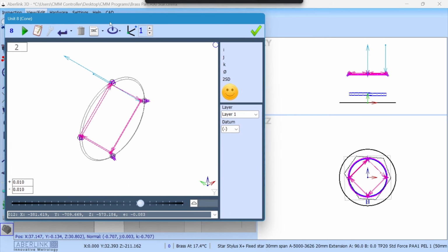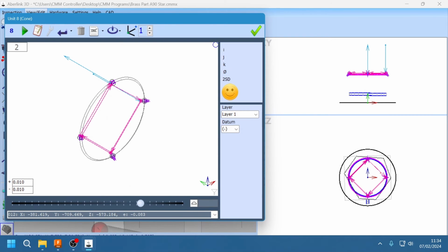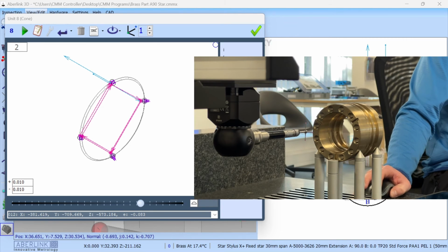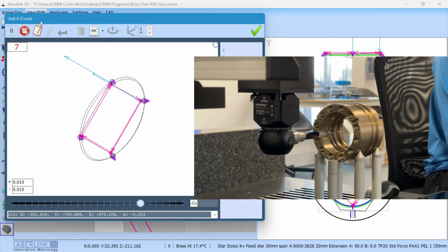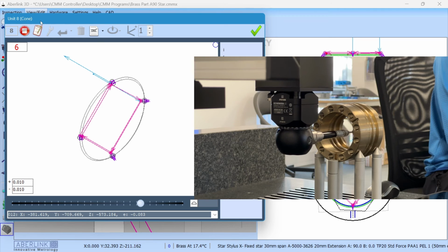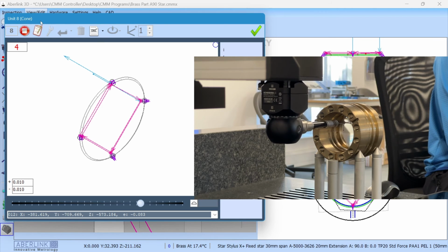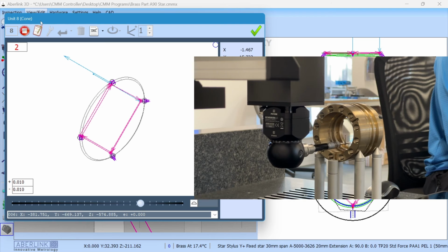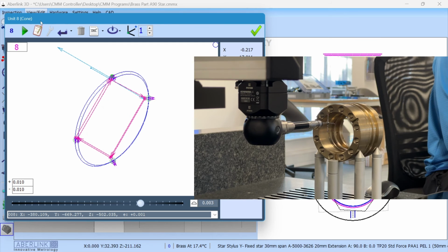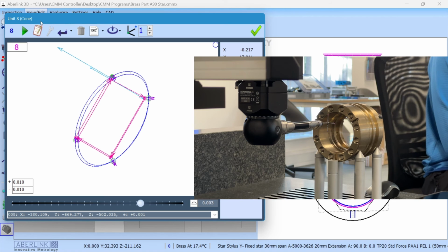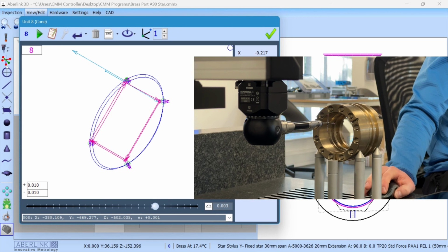So what I'll do now, again you can see this with the feature, I'll turn the camera on, which is now set up so we're viewing from the back of the job, and then when I press play you'll see it safely navigates through the back of the job, goes and measures the initial depth on the cone, now switches to the second depth before taking the final point and exiting out through the back of the job. So it's done all of that automatically for us based on the 2 clicks, and again the safety move in and out is set correctly via using the Z- offset prior to opening the feature and then locking the padlocks.